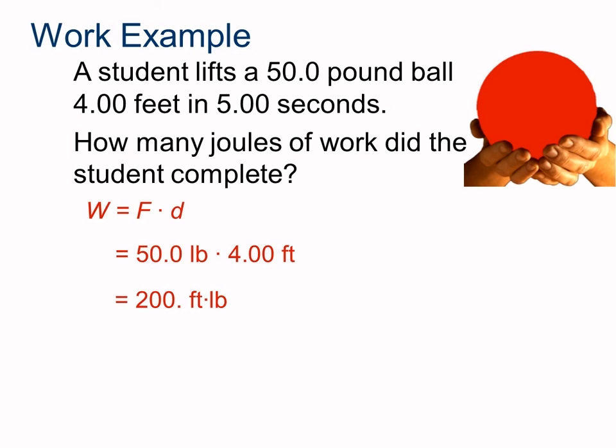Now, if you've watched the previous videos, you know that torque is also in foot-pounds. So are work and torque the same thing? No, they're not. As a matter of fact, torque is maximized when force and distance are at 90 degrees to each other, when they're perpendicular. Work is not that case. Work is maximized when force and displacement are parallel to each other. So that's one big difference. Another big difference is work is a scalar, torque is a vector. Another difference is work is energy, and torque is about the ability to make things spin. So work and torque are different concepts, but they do share the same units in the imperial system. They don't in the metric system, the SI, Système International.